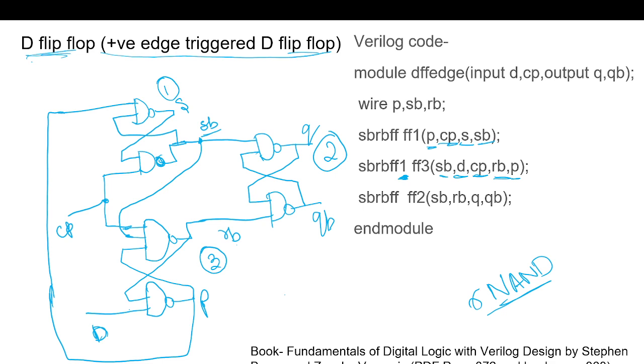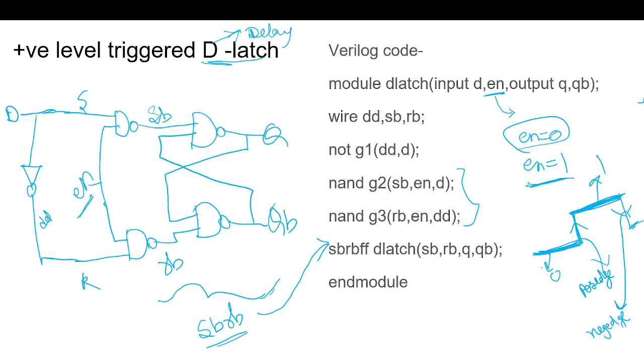If I'm not wrong, 4 NAND gates are enough to build the flip-flop, right? I think this is one of the optimized versions they have given in this book. The other version will be: we need this circuit with 4 NAND gates, and another 4 at the slave stage. So maybe I need 8, plus some inverters, if I'm not wrong.